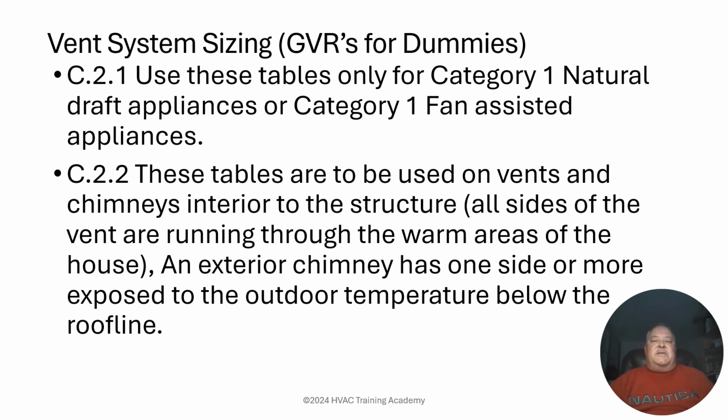But our code says if we drop a chimney liner down a chimney that has one or more sides exposed to the outdoor environment, it no longer sees that chimney as being an exterior chimney and allows that to be used for many different applications. In codes previous to the one we're currently on, they made it an option whether the technician would drop a liner in certain situations.